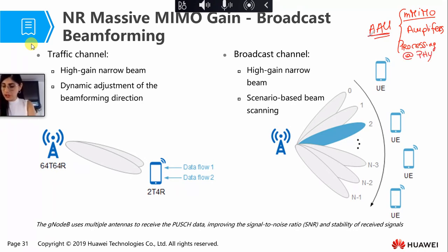So these are the new RF modules which are used for 5G. And as communication interface with the BBU, they support both the, let's say, standard CPRI and also the enhanced CPRI, which allows a rate of 25 gigabit per second, while the CPRI usually allows a rate of 10 gigabit per second.